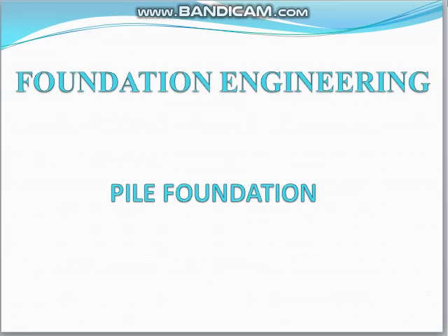If the results of site investigation show that the soil at shallow depth is unstable, or if the estimated settlement is beyond the acceptable limit, then also a pile foundation will be adopted.